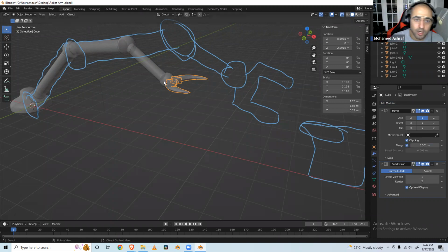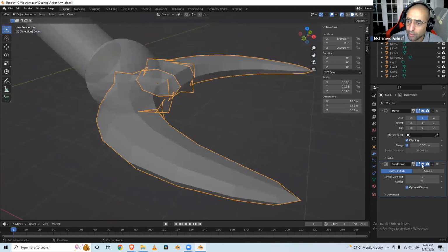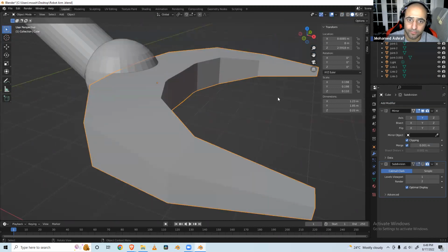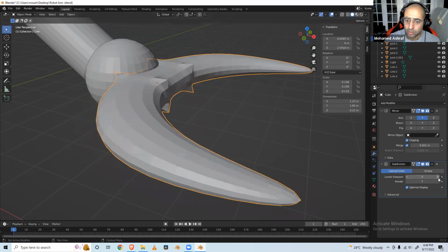And if I zoom in, you can see that before, and I can actually switch it on and off. You can see that right now, let me actually close X-ray too. Right now, it's harsh. There's 90-degree angles. There's a lot of different edges and things like that. And once I turn on subdivision, even if it's just subdividing the one time, it's a game changer. It makes things look cleaner. If I make it twice, it looks even cleaner and cleaner. Let's bump it up to 4. And maybe that's why my Blender keeps crashing.